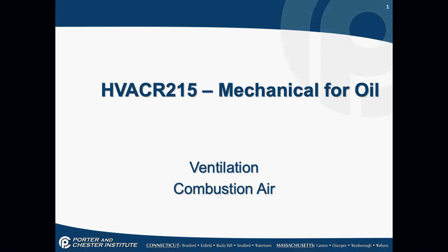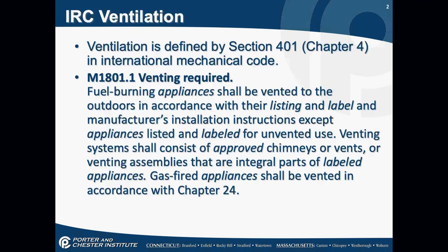Now, ventilation is required. Does the combustion process require air? Yes. It's a major requirement of the combustion process. So ventilation is defined in the International Residential Code, under Section 401 in Chapter 4. Venting is required.